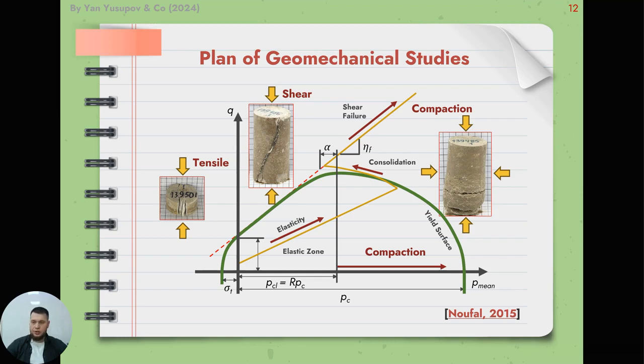So laboratory core testing provides evidence of this behavior. Experiments also show that rock volume decrease with volumetric load leads to material stiffness increase. For pore compaction, the poroelastic plastic deformation cap model must be applied. But we will discuss the failure criteria in the next lectures.